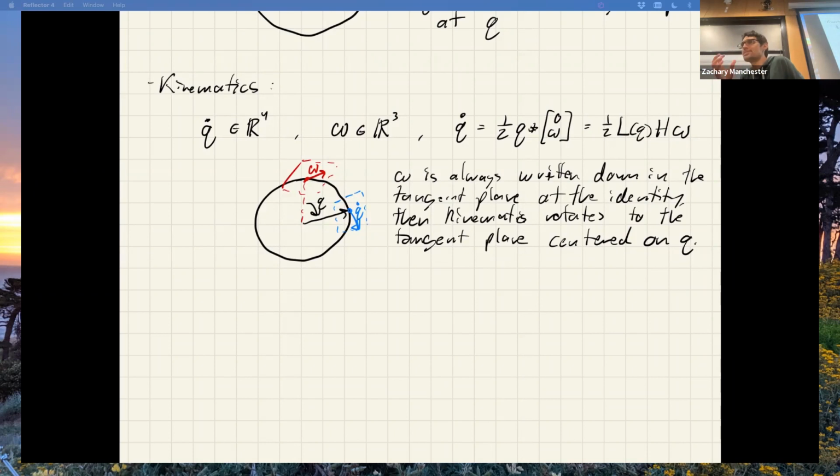The best way to think about these things is as rotation matrices. If you think about them as matrices, you won't go wrong. They compose via multiplication. They don't commute. You can't just add them together. Every time you see a rotation or an attitude or a pose, whether it's a quaternion or whatever, think about it as a rotation matrix. You've got to multiply them. That'll get you the right idea.